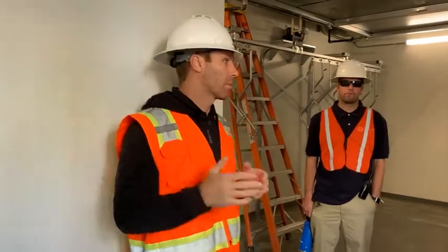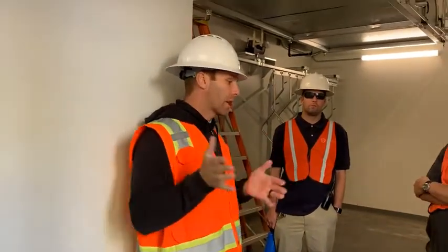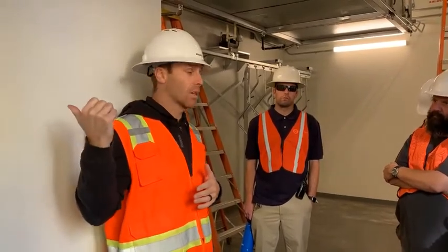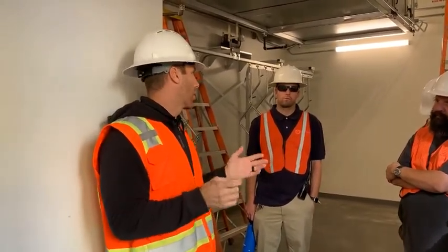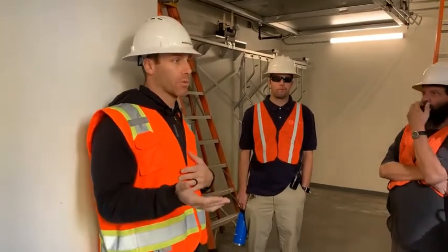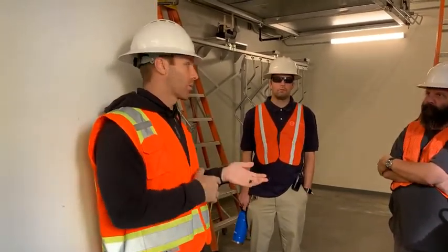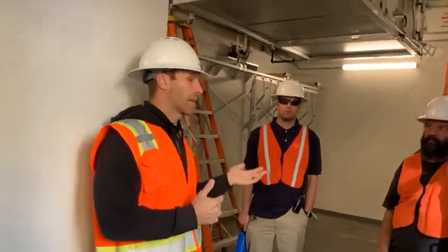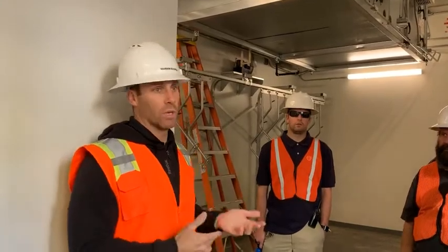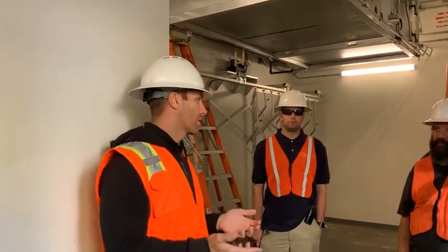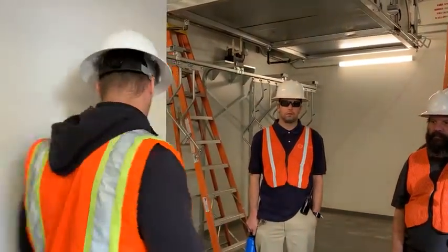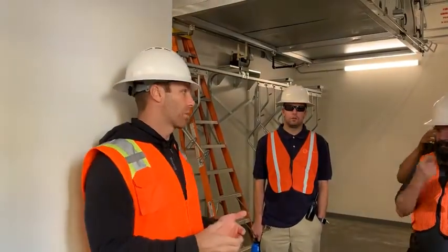But the Eclipse, what we do is we attach it to everything, so that way we can plug into that Eclipse, or realistically, we can Wi-Fi into that Eclipse and change programming to the whole building. We can change the time schedule for the exterior from astronomical to specific hours, or vice versa. If we want to extend the time delay on the sensors or lower them, we can do that as well. All those options are available through the Eclipse for the whole building. And that way I don't have to go into each individual room, take out a wall switch, and program it.